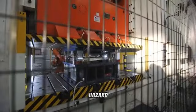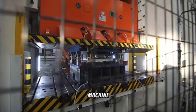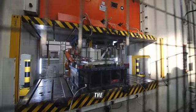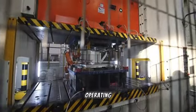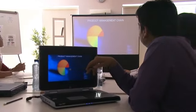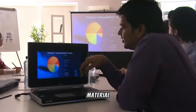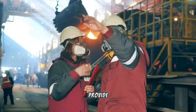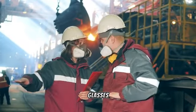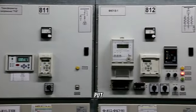For the second hazard, which was entanglement with moving parts, we can put in place a control such as installing machine guarding or using safety barriers to prevent anyone from entering the danger zone of the machine while it is operating. For the third hazard, improper handling of material or tools, we can put in place a control such as providing training to employees on how to handle the material and tools correctly. We can also provide them with the necessary personal protective equipment like gloves or safety glasses to minimize the risk of injury. So those are some of the controls that can be put in place.